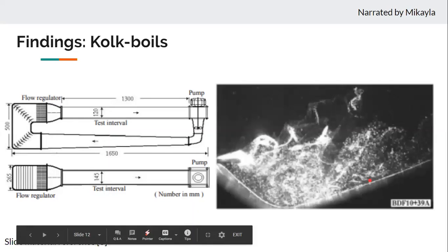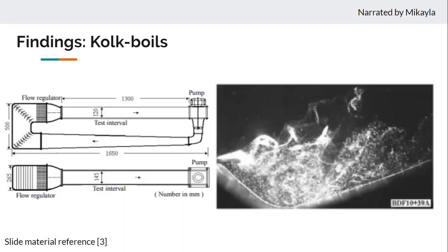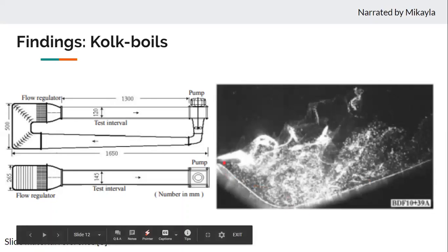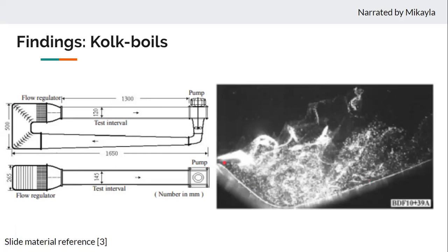To capture this phenomenon, they coated flumes connected to a pump and flow regulator with waterproof sandpaper. Observed was an area mimicking flow separation called free turbulent area, along with a separated region below that, or trough turbulent area, acting as an ejection cushion that impedes sediment sweep and pushes sediment toward the suspended load.